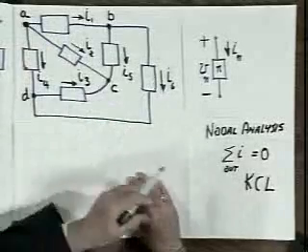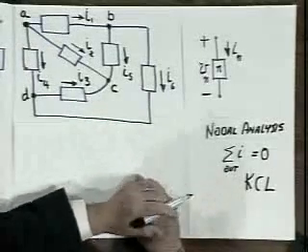While I need, for the purposes of this analysis, to have definitions for all of those currents, those definitions are entirely arbitrary. That is, everywhere here that I've shown an arrow in a particular direction, I could equally as well have shown it in the other direction. The choice you make for variables in this analysis has nothing to do with the results that you get. You will get what results correspond to the physical behavior of the circuit. So keep in mind that the current directions I've shown are entirely arbitrary.